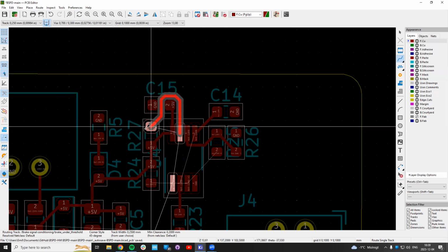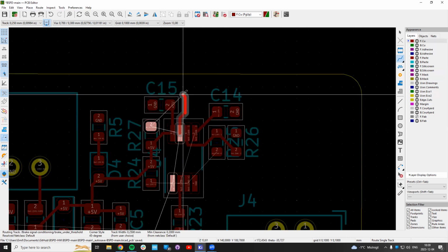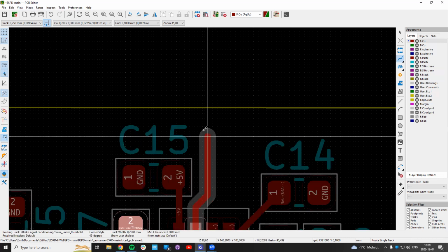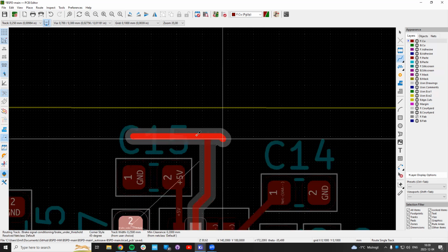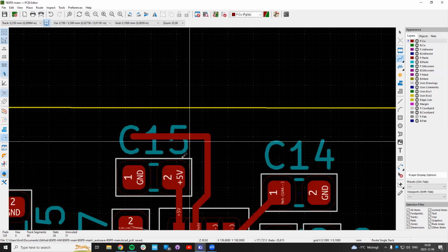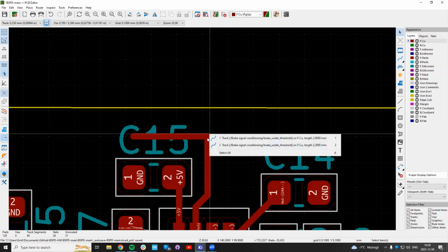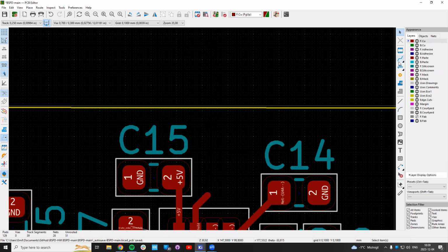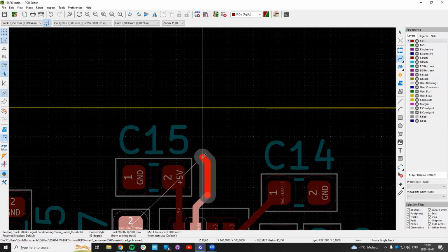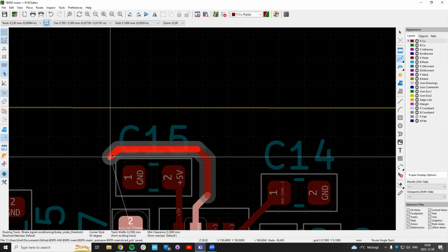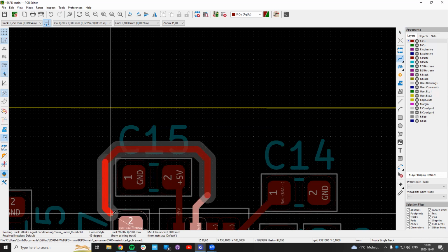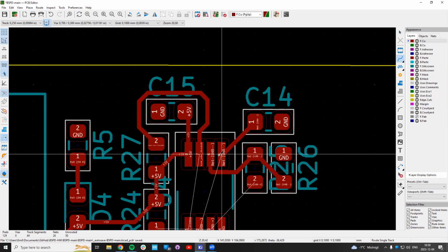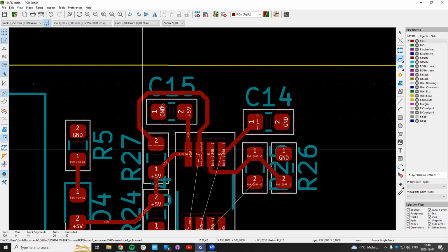And now, yes, I should say this now. A common error you can make is you do this. So what's wrong with this trace? Don't do 45-degree bends. With 45-degree bends, the width will be all weird. You have some crazy phenomena that you can read about yourself happening. If you do the 45 degrees, it's a bad habit. Don't do it. Okay, so that's why we do this.